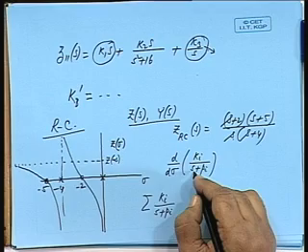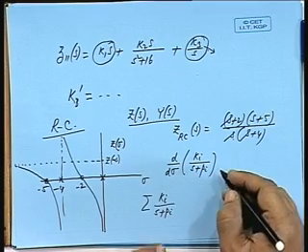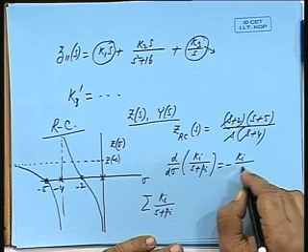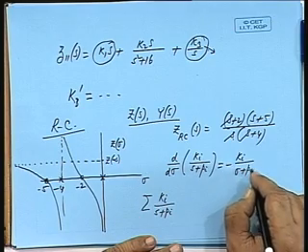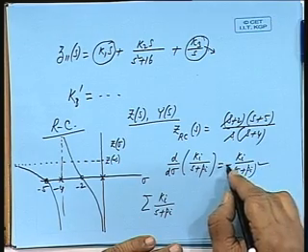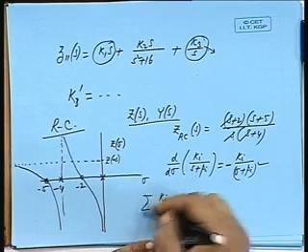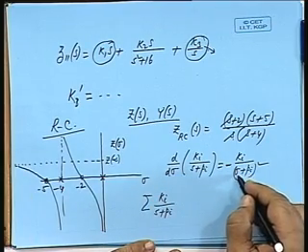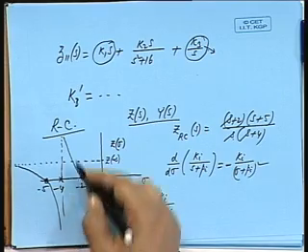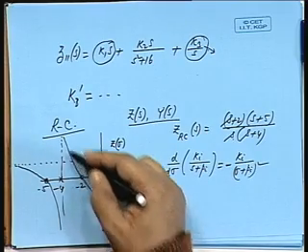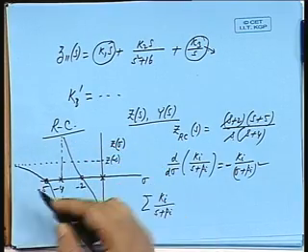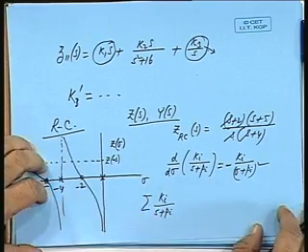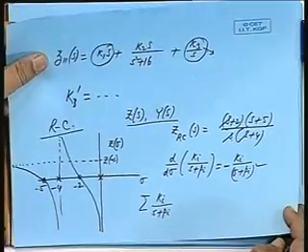You will find this gives me minus Ki by sigma plus Pi whole square, which will always give me a negative slope, irrespective of the value of sigma. So, here it has to pass through 0 with a negative slope, and the curve has to be this way. This is the nature of Z in the case of an RC network.